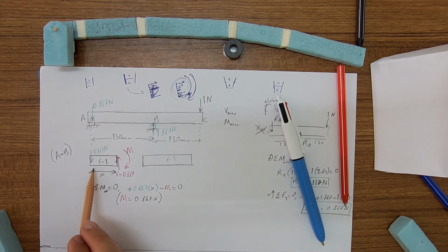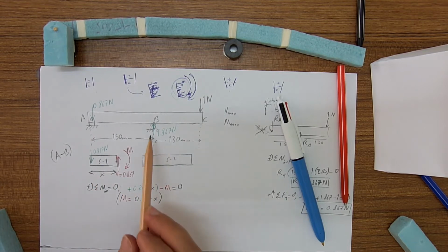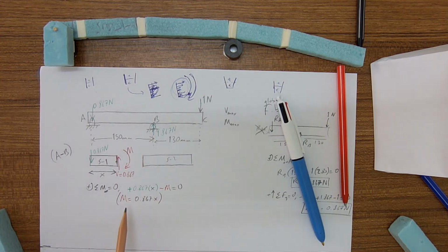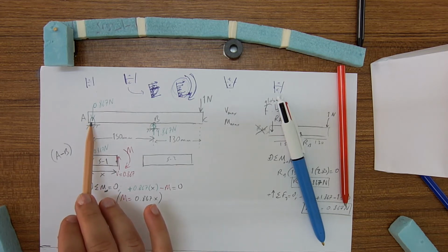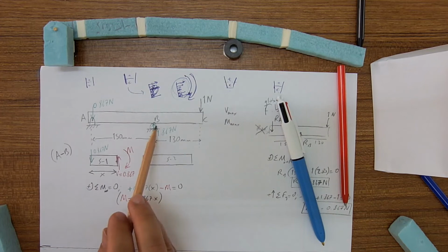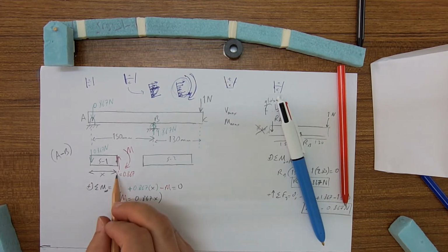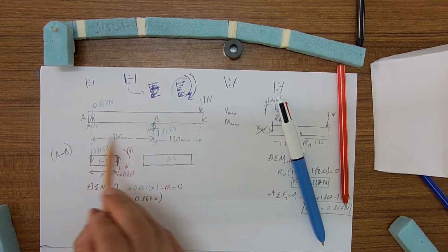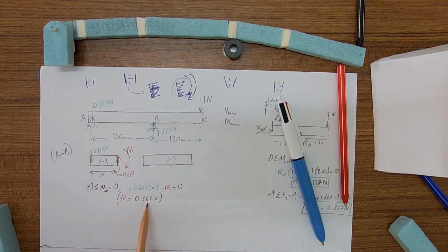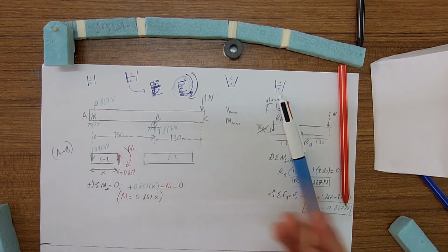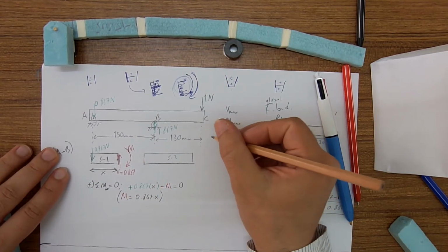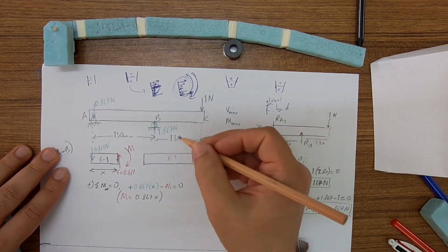As the size of the segment increases, the internal bending moment increases. But this equation is valid until the next discontinuity, which is point B. So this equation is valid between the points A and B. The V is constant within this region, and M is linearly increasing within this region. Going to the next segment, next region, BC.